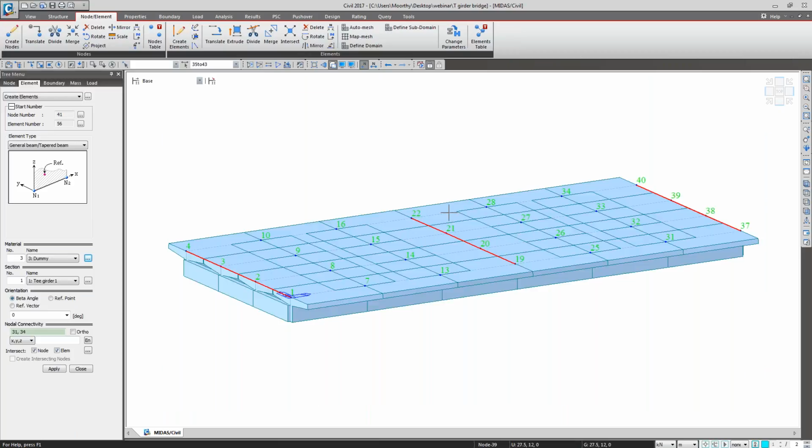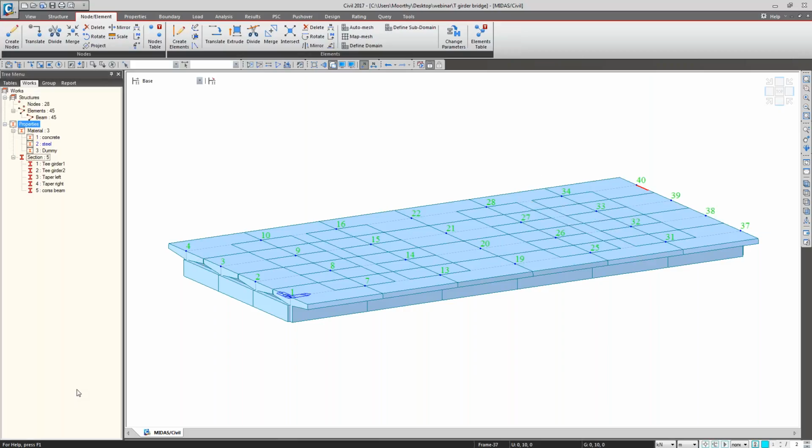The dummy members will be useful to make your grillage model. The grillage modeling concept is to make a smooth load transfer from one member to another member, which is modeling-wise better than your single line geometry. Fine. So modeling is done.